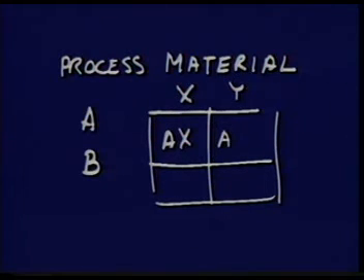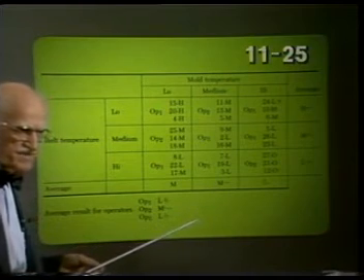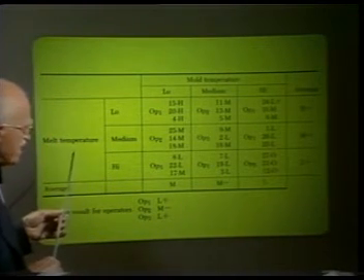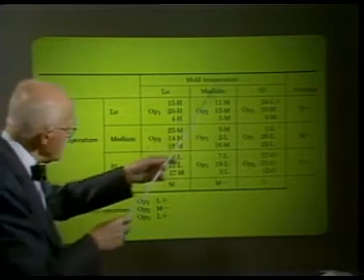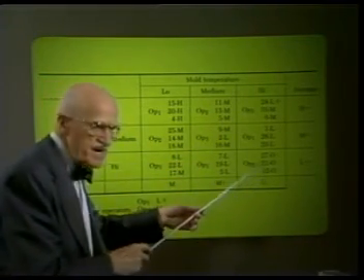Analysis of the horizontal and vertical sums tells us a good deal about the relative effects of these variables and their interactions. If we add a third variable, we need a more complex design. We saw an example in the die casting case which used a 3-by-3 Latin square design. Here, the combination of high mold temperature and high melt temperature gave the least porosity.